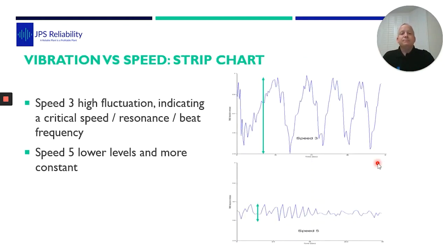But what is causing this to have the resonance problem? We looked at the data another way. So here on a similar pump, we have set point 3 and set point 5. So on set point 3, you can see, if you imagine this coming up, it's all going bum bum bum like this. So that motor there, when it's running at set point 3, highly directional, is juddering and a motion coming around. You put up to set point 5 and it's a lot smoother. So down here, you can see it's a lot smoother motion. So we're getting this data up to try and show, to explain to the asset owner that the problem is resonance.